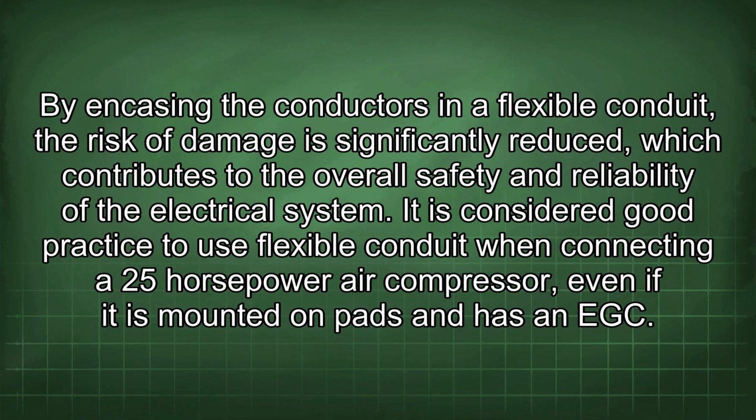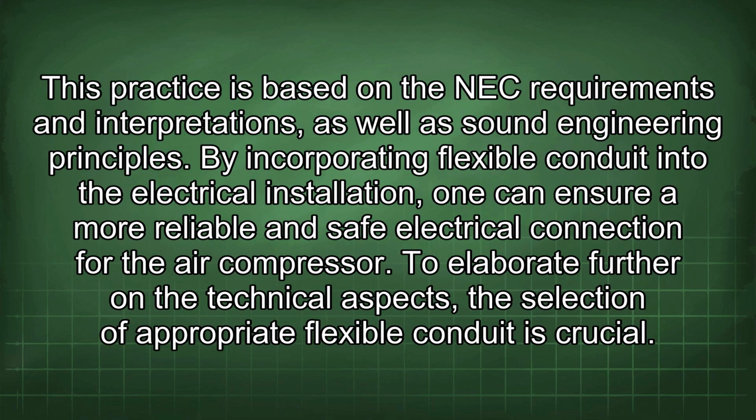It is considered good practice to use flexible conduit when connecting a 25 horsepower air compressor, even if it is mounted on pads and has an EGC. This practice is based on the NEC requirements and interpretations, as well as sound engineering principles. By incorporating flexible conduit into the electrical installation, one can ensure a more reliable and safe electrical connection for the air compressor. To elaborate further on the technical aspects, the selection of appropriate flexible conduit is crucial.